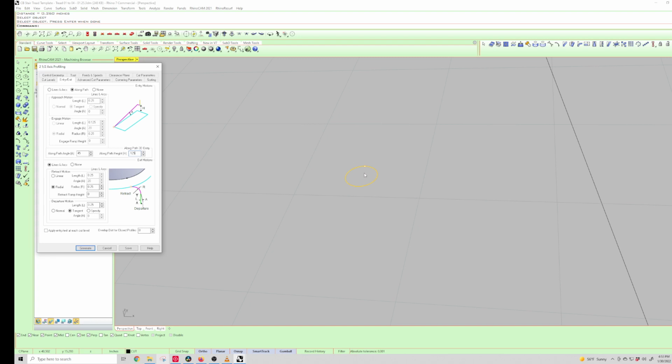A lot of times if you have a plunging end mill, you can get away with that, but it's also really good to be able to have the tool remove itself and clear any dust and stuff that's in there, and then re-enter at an angle again.